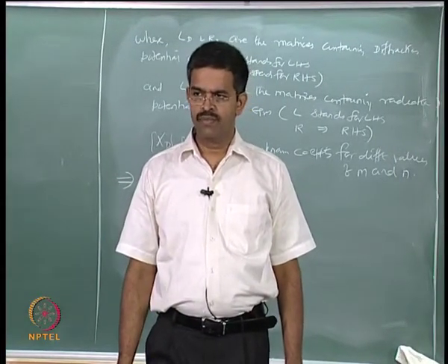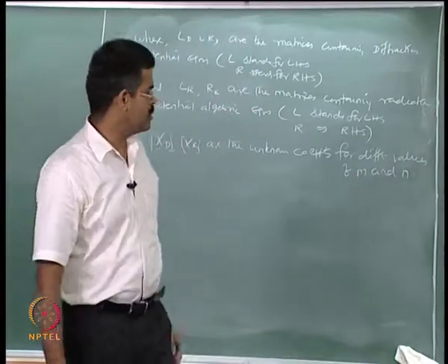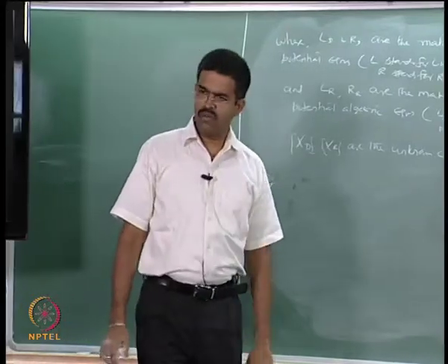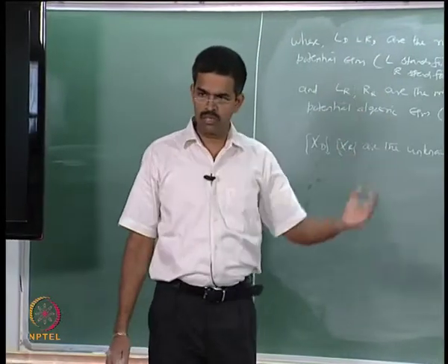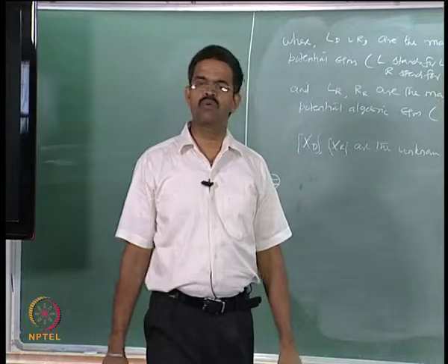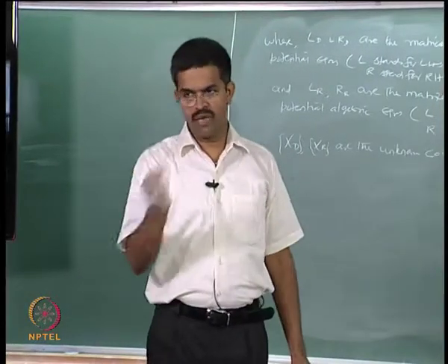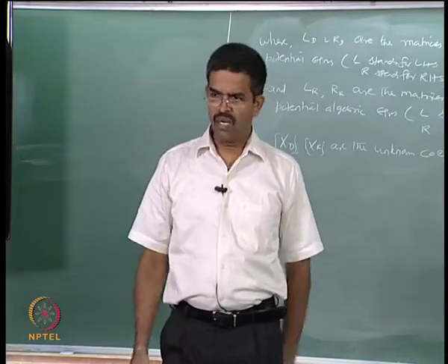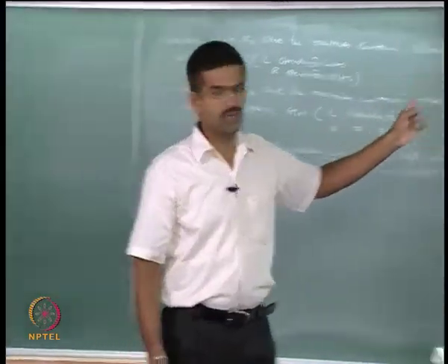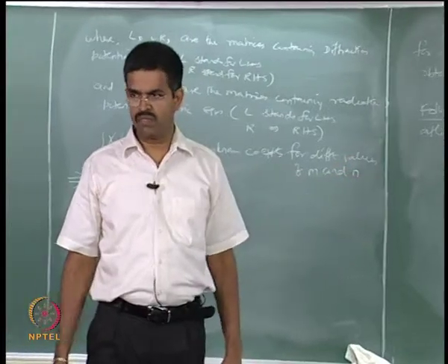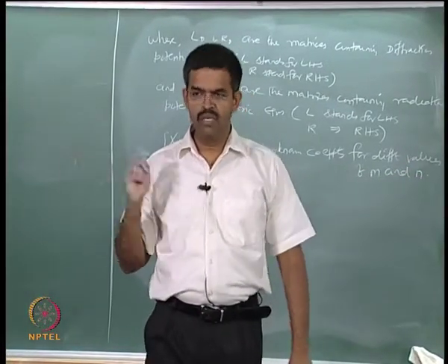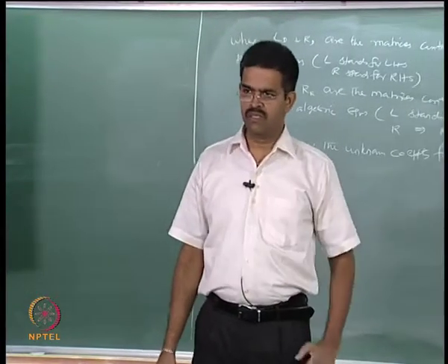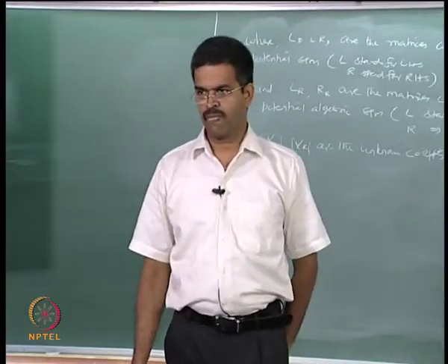Okay. Once you know this, you can apply this on any porous structure, because now you know the velocity potential. You can easily find out the forces generated by this velocity potential in the respective regions 1, 2 and 3, and accordingly sum them in the respective degrees of freedom, which are surge, sway, heave and pitch, and do a conventional dynamic analysis and find out the responses.